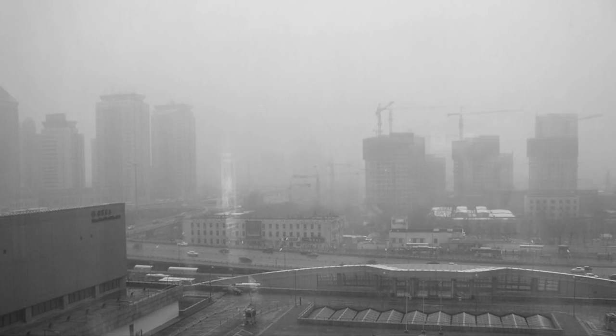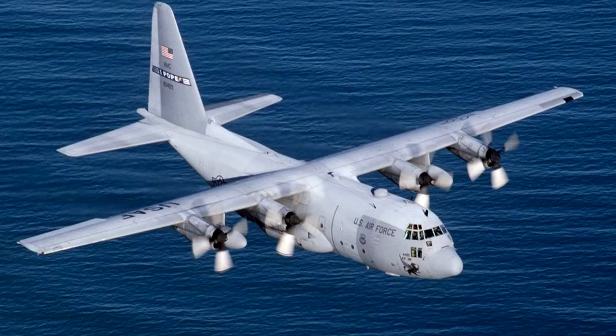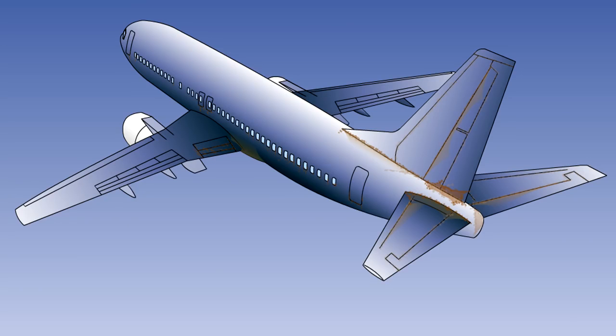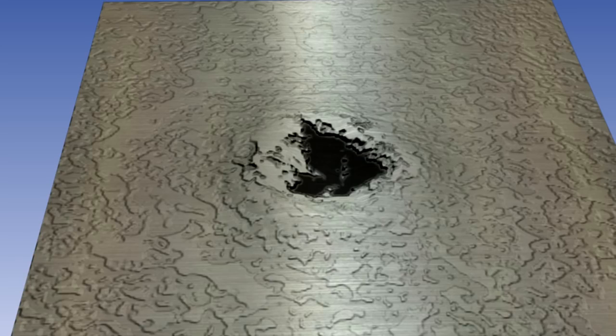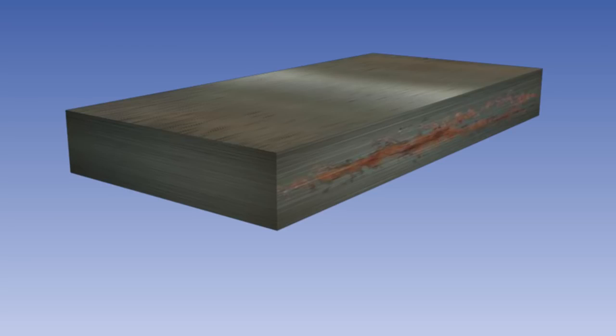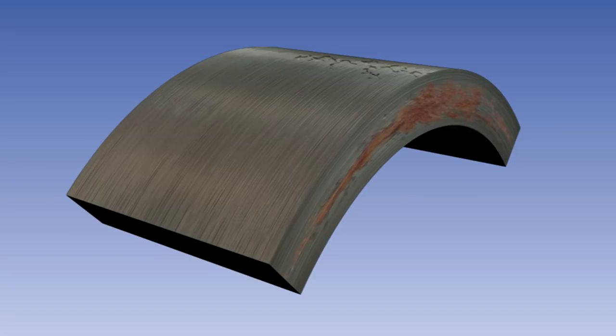The degree of corrosion is proportional to the amount of impurities in the water, the impurities being due to industrial pollution which has high sulfur content, or by airborne salt particles when operating over the sea. The resultant action is that the metal undergoes a chemical change. The attack may extend over the entire surface of the metal, or it may penetrate locally, forming deep pits, or even follow grain boundaries inside the core of the metal. The weakening effect can be aggravated by stresses in the metal due to external loads, or there may be residual stresses from the manufacturing process or method of assembly.